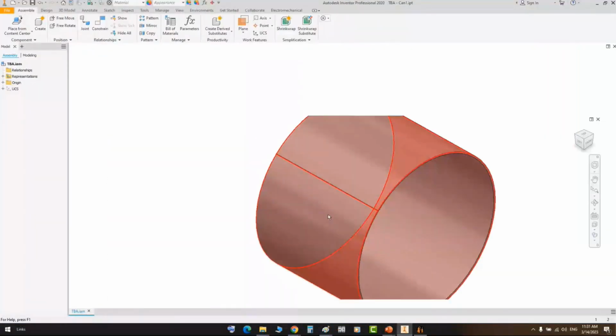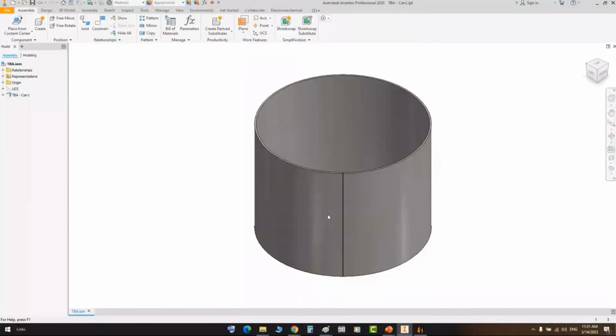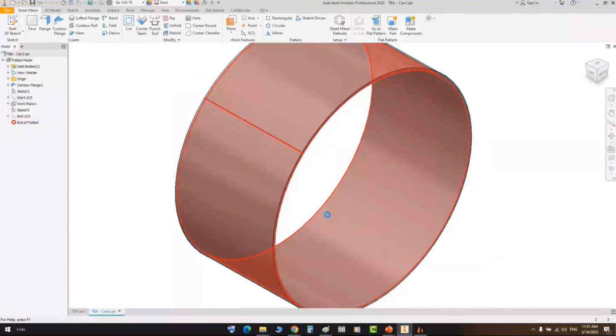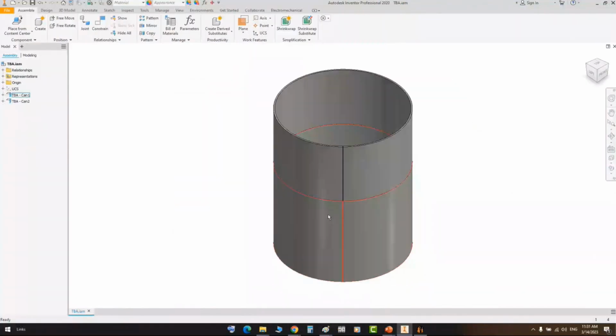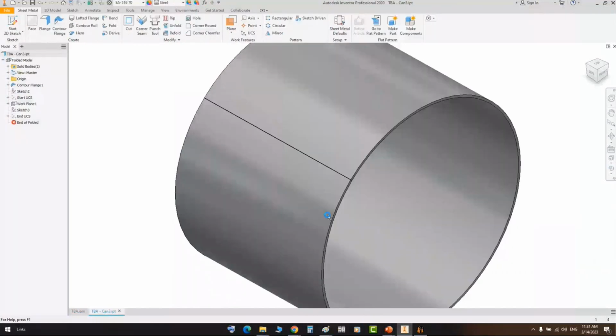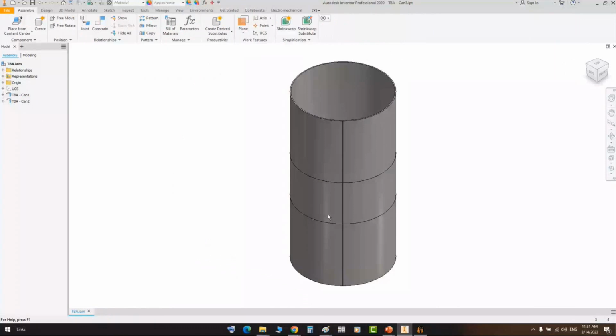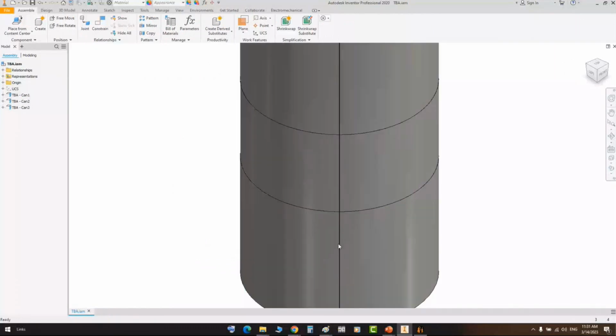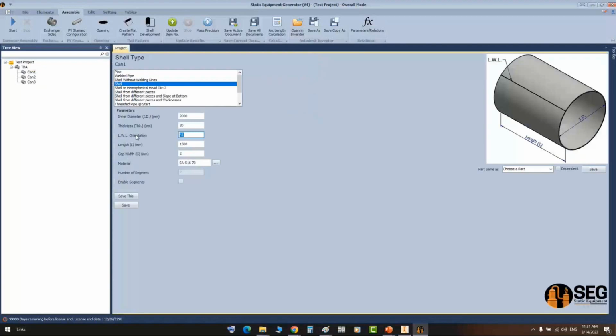And here, if you would like to change the longitudinal welding line orientation, there is a text box inside each shell. So you will select the node from the tree and redefine the orientation of the welding line. For example, here, the first course longitudinal welding line orientation is at 45 degrees. You can change the orientation of this one to 0 degrees.